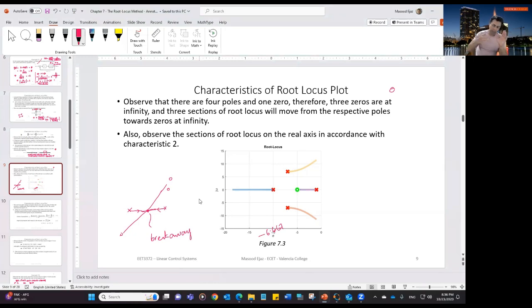So you're just going to combine the first root together, second root, third root, fourth root together, and connect them on the S-plane to get 4 root loci. The first step is, of course, to put the poles of the characteristic equation when K is equal to 0, and the zeros of the characteristic equation. And then all the poles will be combined together, as you can see over here. So that is the root locus.